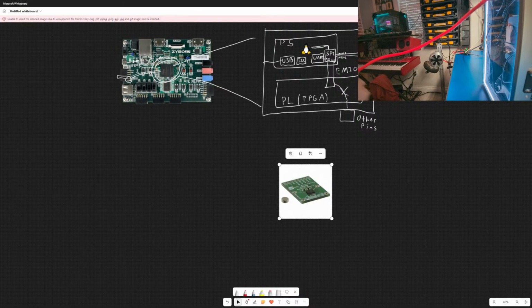Oh, and there's also another benefit to that AMS encoder. I mentioned this before, I keep saying absolute encoder, absolute encoder. What is an absolute encoder? An absolute encoder is an encoder that remembers its position no matter where it is. So if I attach this to the motor, and let's say all the circuitry is off, and then I just turn it on for the first time, I will know that I'm at 90 degrees and this is at whatever degrees, right? It'll know it immediately.